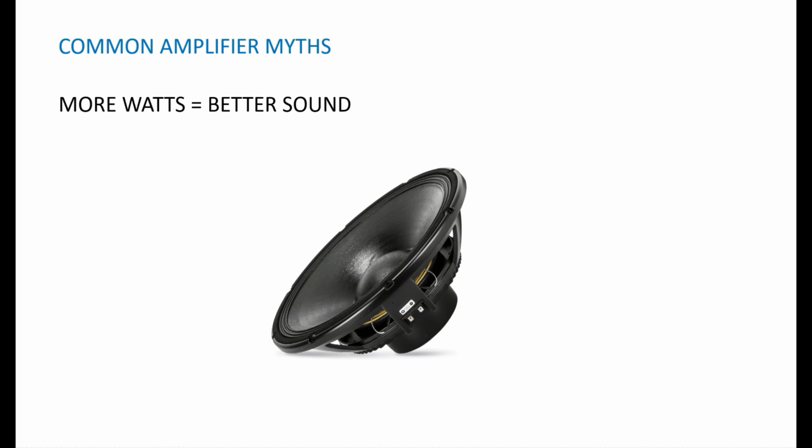The next one is a bit of a strange one. It's this belief that more watts equals better sound, right? So, once again, I'm not sure where this comes from, but it's kind of like saying bigger speakers will sound better. Now, there's a question of how big do my amps need to be in terms of output, and yes, some headroom is beneficial, so your amps don't have to work super hard, but that's a completely different topic. But having 500 watts per channel on a 10 watt speaker won't make them sound better.